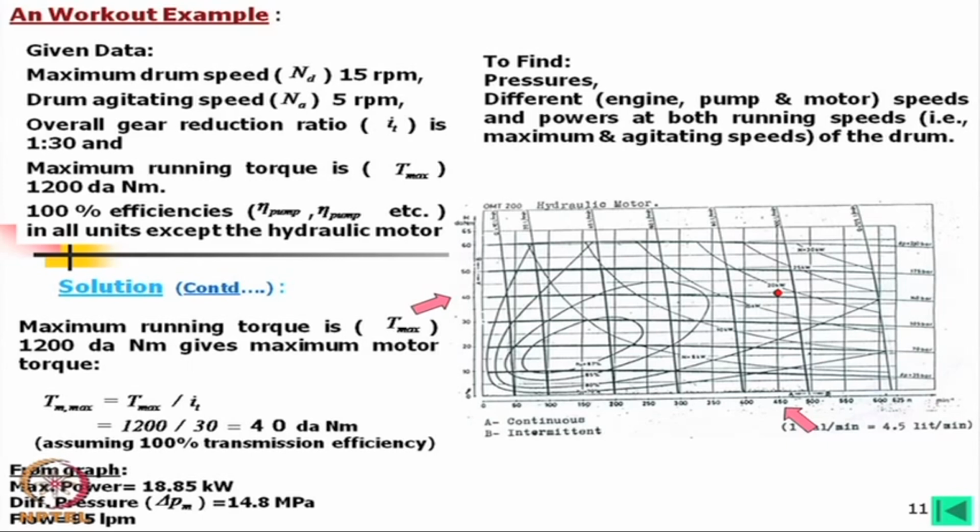So the oil in pressure should be higher. To know the actual pressure input to this motor, we need to know the output pressure. In a closed circuit, it will always be there, so we have to calculate considering these two pressures. In an open circuit, we may consider that the outlet pressure is very low. Anyway, this remains unknown in this problem.